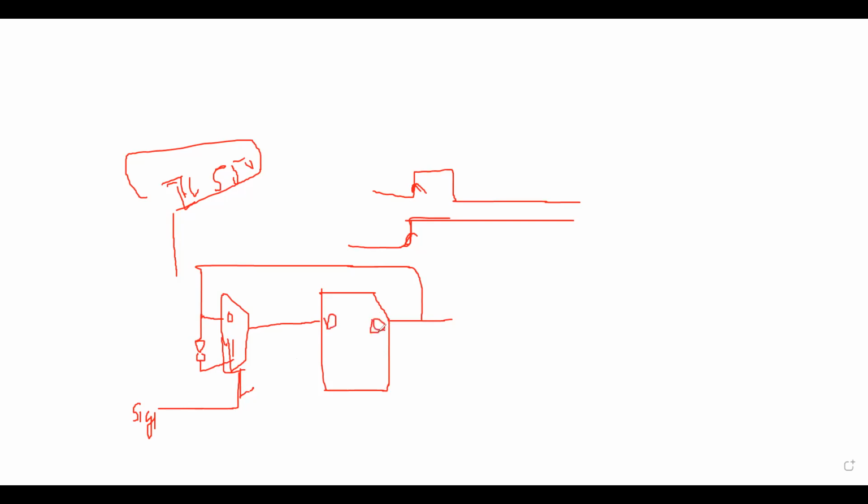This will work? So whenever my signal is 1, the previous value of this flop would be 0, correct? So this 0 will come here, and up to here it would be 0, and from here it will become 1, correct? This 1 will get passed on to this value. So we have 1 over here.